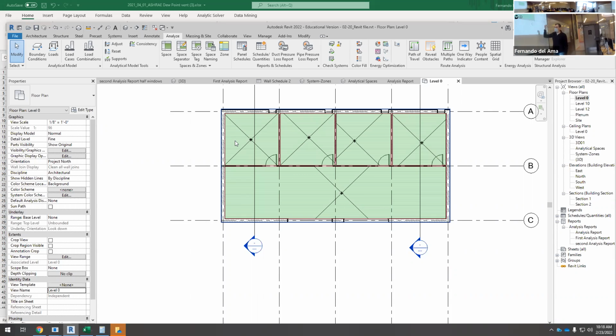But anyway, if the Revit figure were lower than the Excel figure, I would select the Excel figure just to be on the safe side, okay? Because I can't afford, if my client is cold and it's working with the heat pump or the boiler at full speed or whatever, and okay, I can't give more power and I'm still cold. What can I do? You're lost. Okay, so when you have two different figures, select the highest, because then you have to design your systems based on that figure.